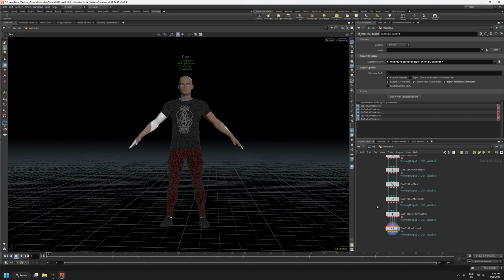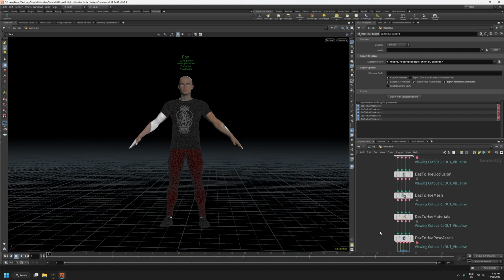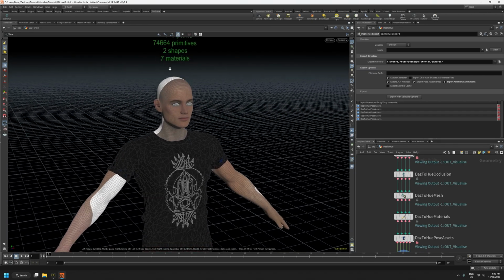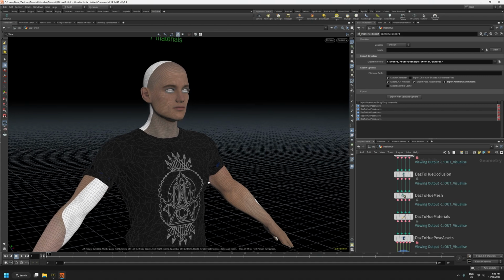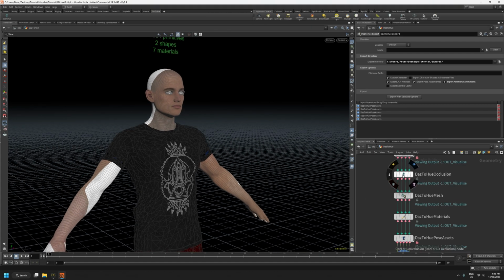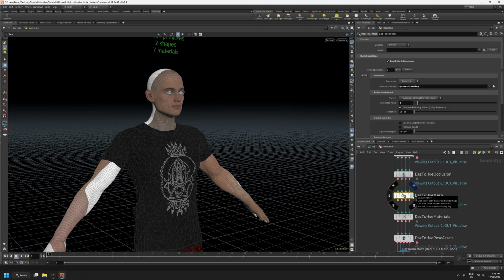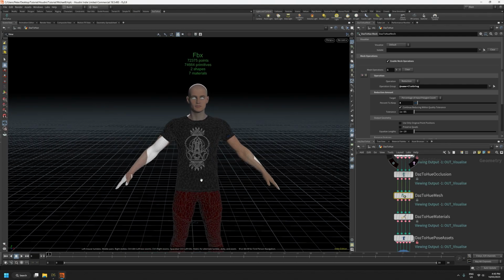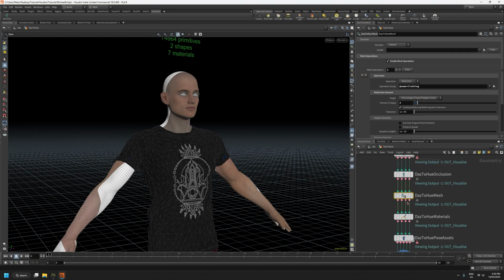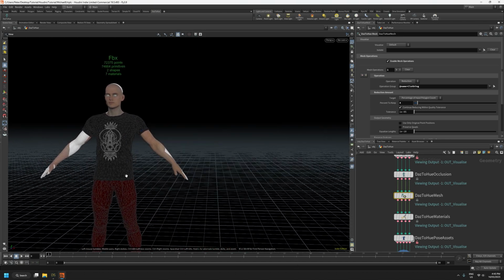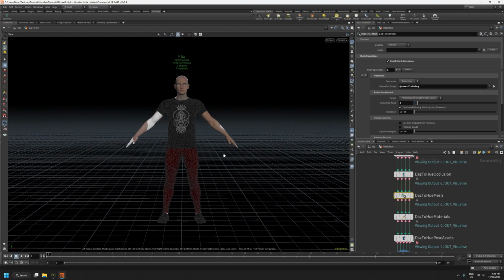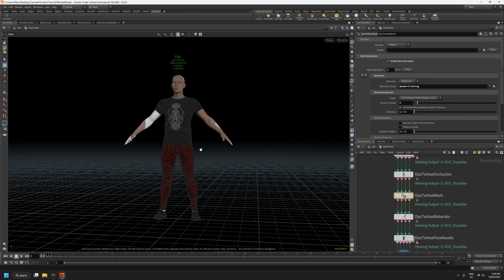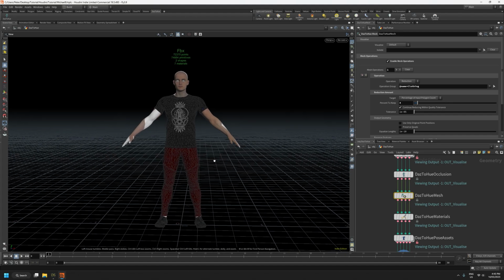So now we're ready to export those files. How long the export takes depends on a few things. Obviously, it depends on the mesh density. The more polygons, typically the slower it takes. But it also depends on the various operations we've performed on the mesh along the way. So the occlusion operations and the subdivision or poly reduction operations all have a slight impact on export times. So even though, for example, we are removing a lot of geometry from the original character, those operations need to be performed twice, in fact, one for the FBX and one for the dynamic cache, and they need to be performed for each frame, so it will have a slight impact, but overall this method is far faster than doing any sort of ray casting, which is what other methods I've seen typically use.